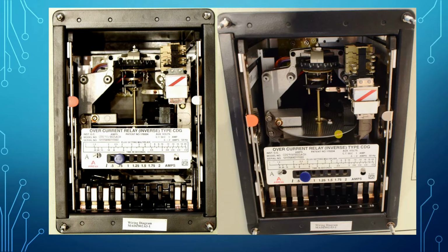This is the disk. This is the braking magnet, and there is a primary winding and a secondary winding, upper and lower, in that form. And this is the spindle. The rod is attached to the disk, and this knob of the spindle moves with the disk. When the disk is moving, the spindle touches this moving terminal, and this is fixed. So this moves towards the back side and gives the signal to the circuit breaker, and the terminals are connected like that.